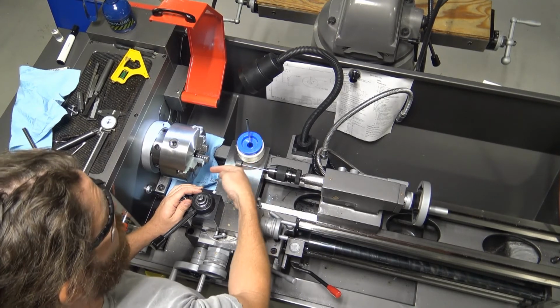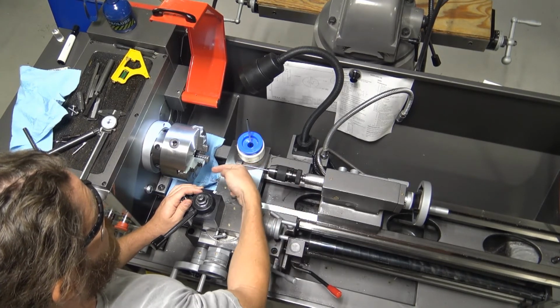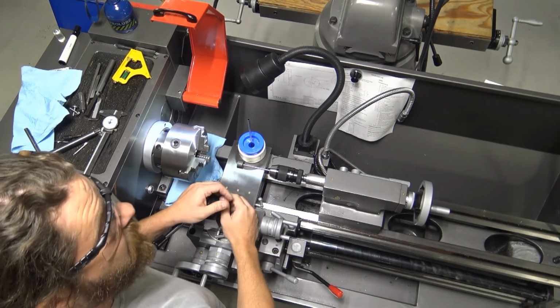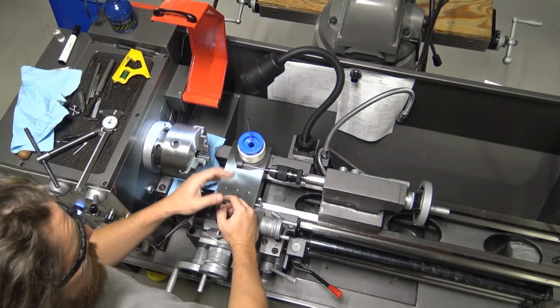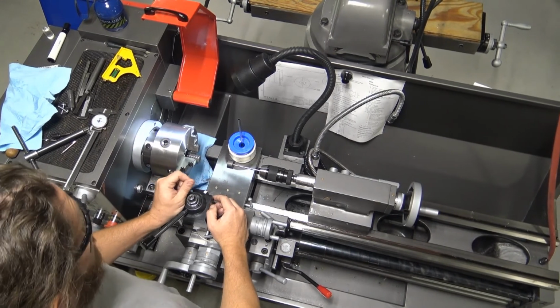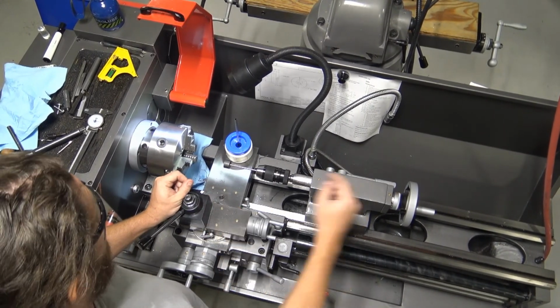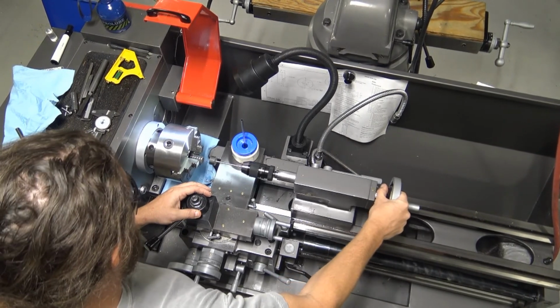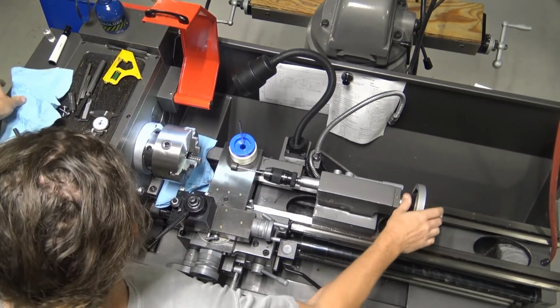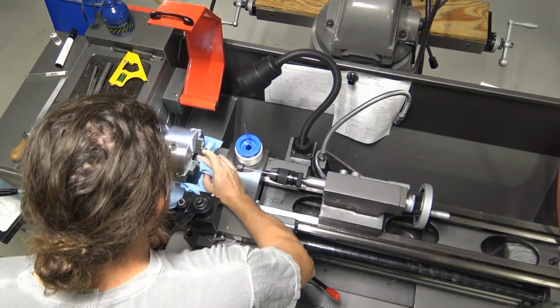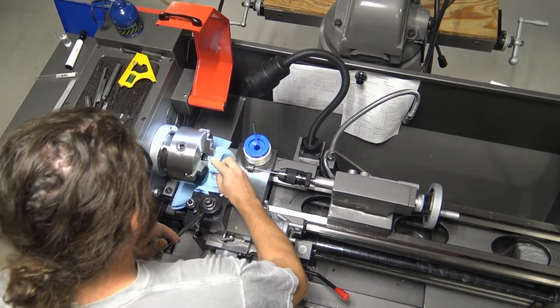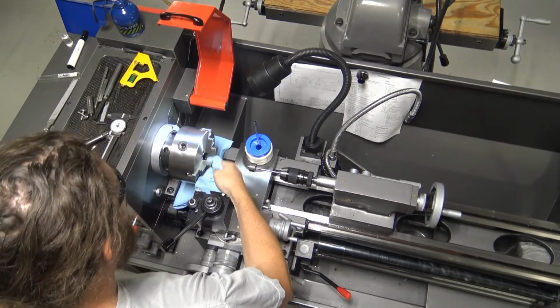Again, I don't want that hole that we just reamed to be off axis in any way, because that's just going to make your flywheel tumble and fumble about. All right, and that's not what we want. So I'll put it here on this reamer and then slide it back. Let me wipe my chuck out a little bit here, so we're not gripping on chips. All right.